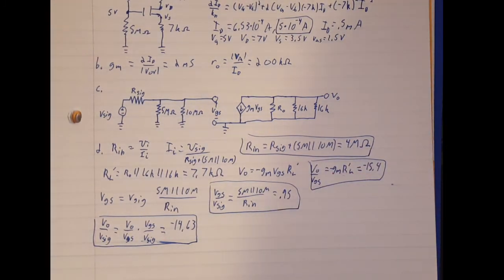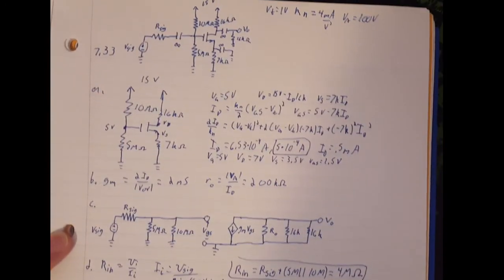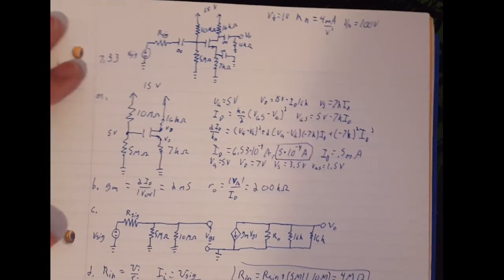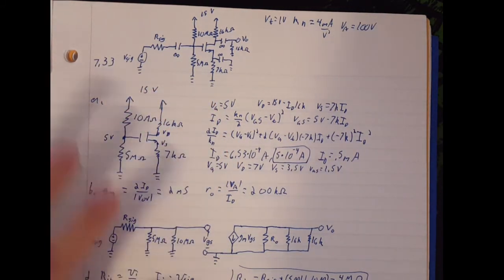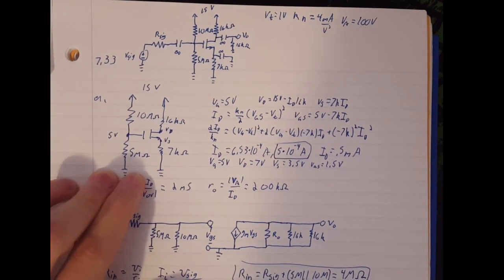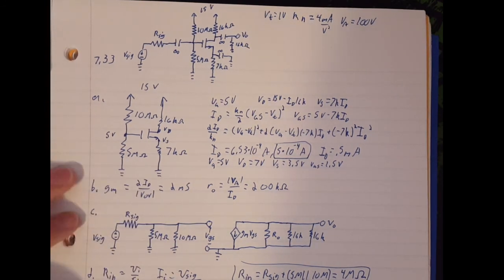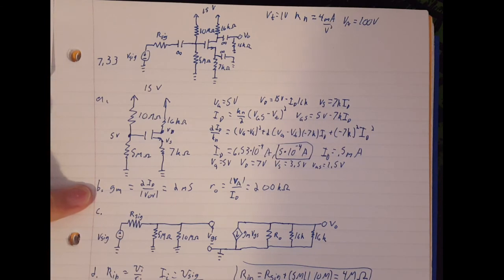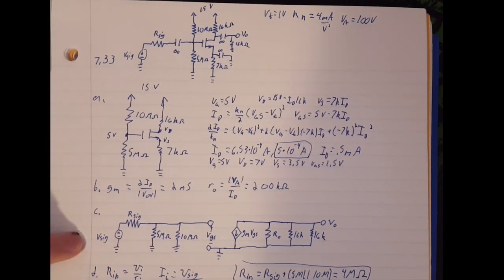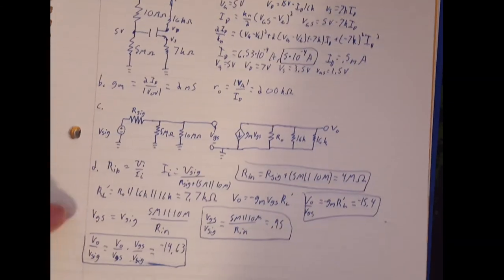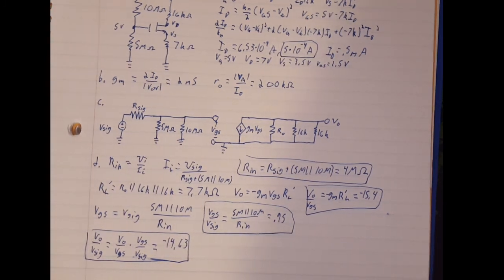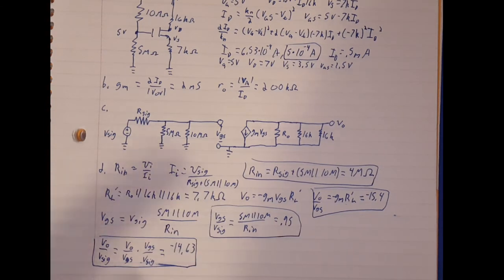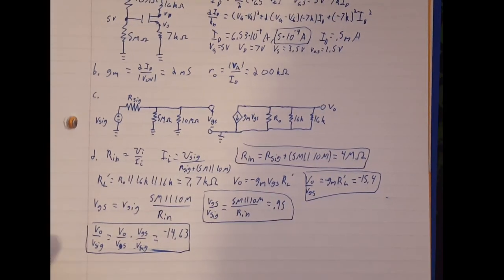And so you see how we go step by step through this problem. You start out with this big complicated mess up here, and then you simplify it to do biasing on it, DC biasing. And then you find the characteristics that let you do small signal, and then you do small signal on it, and that lets you know the gain and Rin. And later on, it will tell you the poles as well when there are capacitors in there.